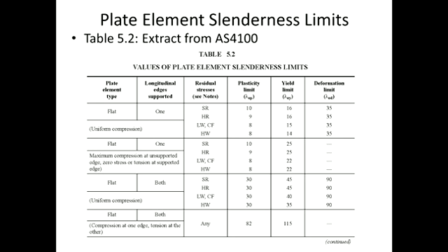And what about this second part here? So we also have a flat plate element which is supported on one longitudinal edge, and then we have maximum compression at an unsupported edge and zero stress at the supported edge. So where would this apply?